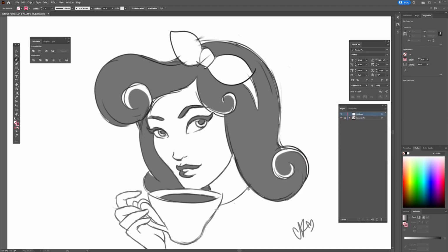With that done, we're ready to make our first anchor point and find a good position. I'm going to start where the hairline meets the little floof part. Click, drag out, and then click and hold, and then drag again to create a Bezier curve. And congratulations, we made our first pen tool line.